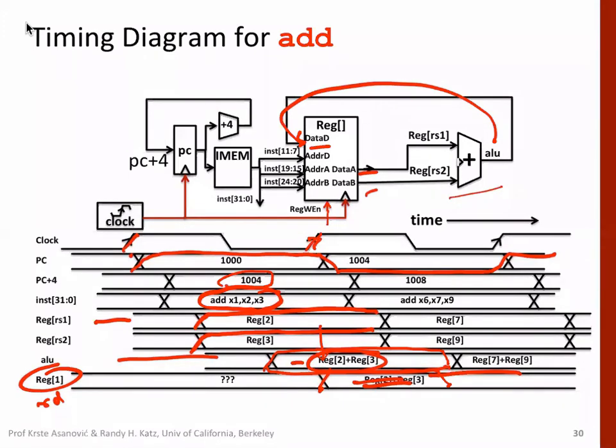What you need to do is just look at each of these timing diagrams. You just have at a clock edge to draw one line and see what the values are and so on, right? Between two clock edges, all combinational logic will work, and you can see what the different values are, and then how you get the output. Only thing to remember is that all these operations are happening before the next clock edge. So at the next clock edge, we have this result available, the summation of the two registers.